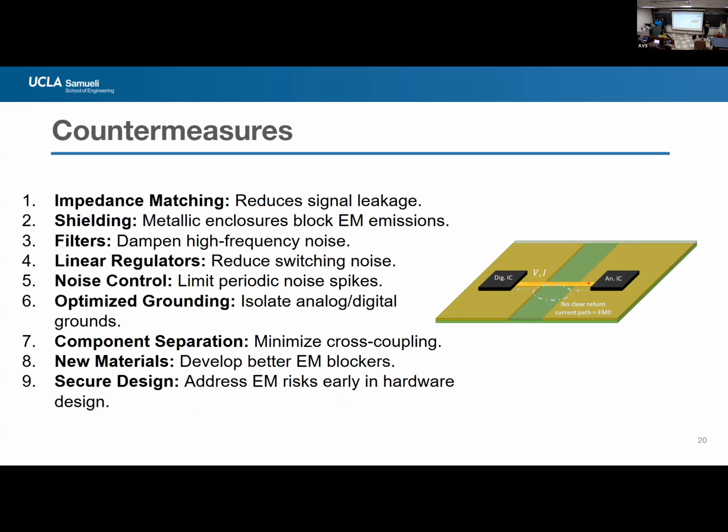So some of the countermeasures that we look at are things like impedance matching. So the impact of signal coupling, capacitive coupling, the impact of high sensitivity often resulting in a low impedance, using metallic enclosures around critical components of the SoCs to block EM waves, line filters to signals and power lines that connect the SoCs that can help in reducing radiation.